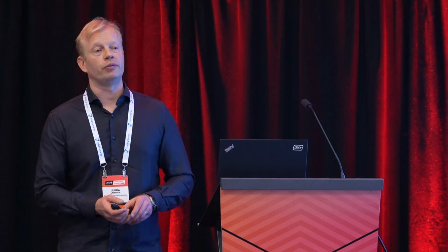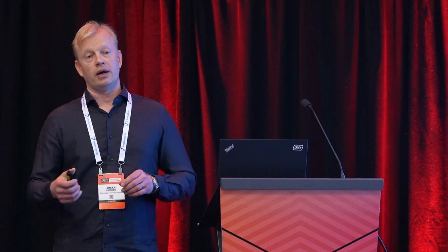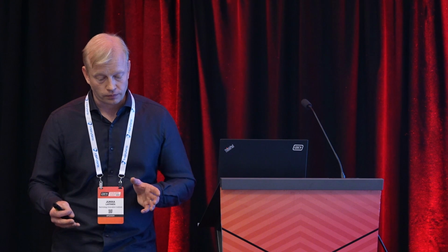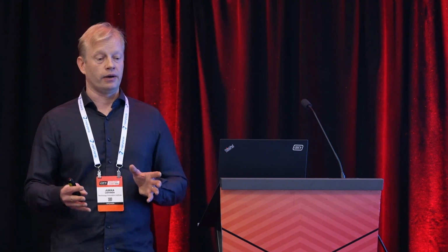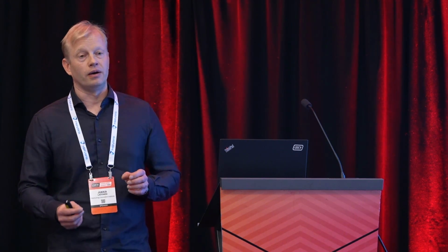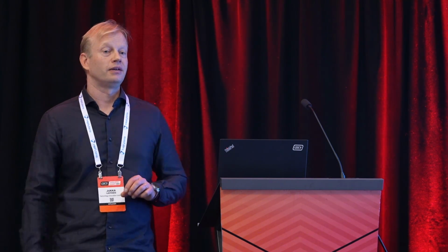There are some things that we had to allocate statically inside uORB, because when you are putting something inside a shared memory object, you have to know the size of the object in advance. So there are some structures that we have to allocate space for, some things that you probably never need. But yeah, mostly from the NuttX side.